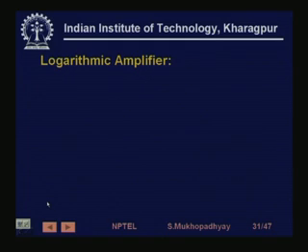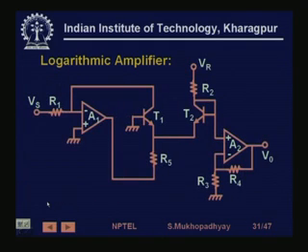Then in some cases, for example, we need to do various kinds of computation. For example, we may be interested in sensing a voltage and a current signal and then measuring power, in which case we need to multiply. There may be cases, for example, in flow measurement, as we have seen, that the flow is actually proportional to root over of delta P, and what we sense from a meter is essentially delta P. So we need to compute root over of delta P.